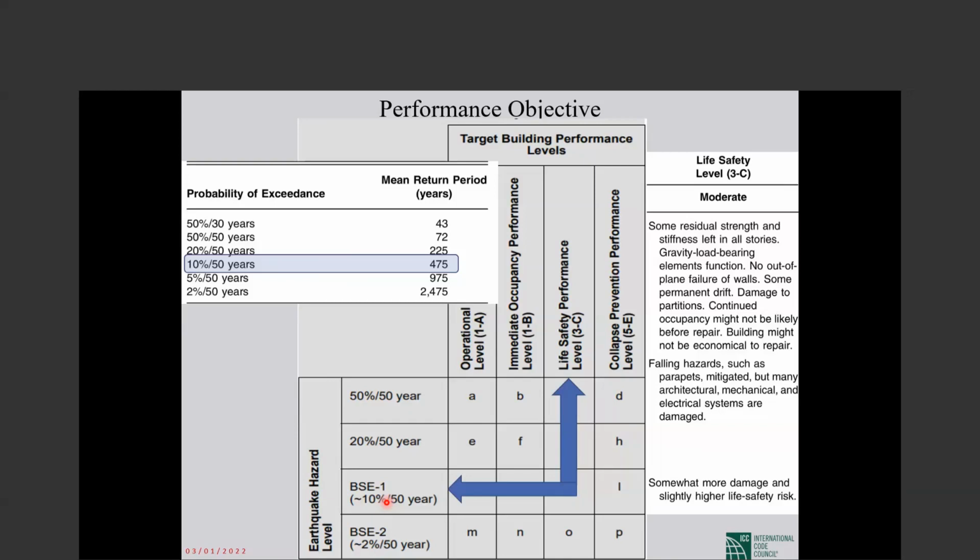Where is the importance factor? Are we treating hospitals and schools the same as ordinary structures? No, in performance-based design, you don't need a prescriptive importance factor.